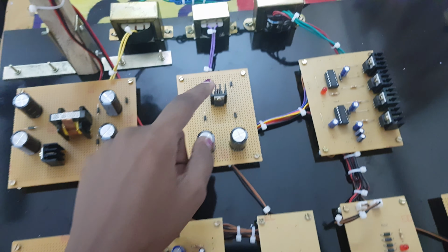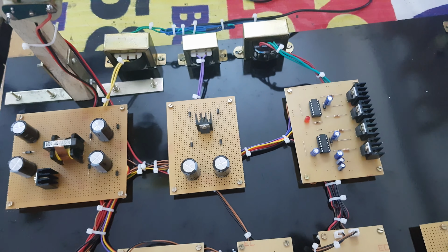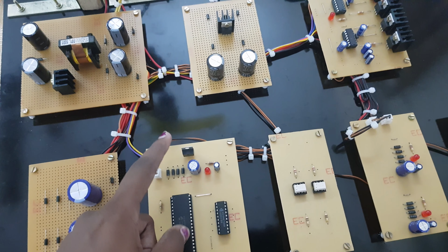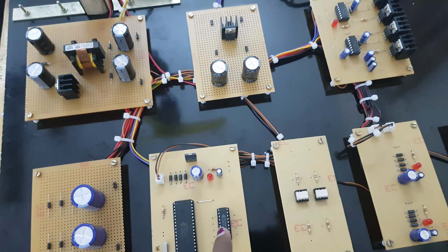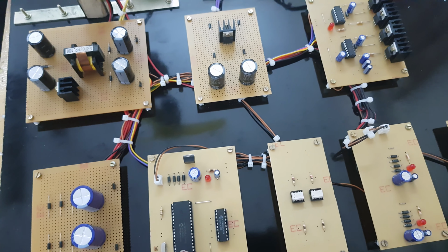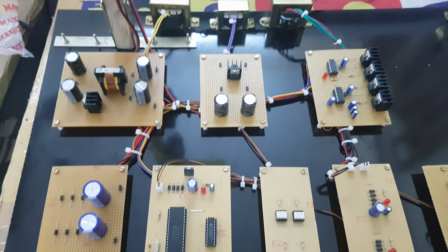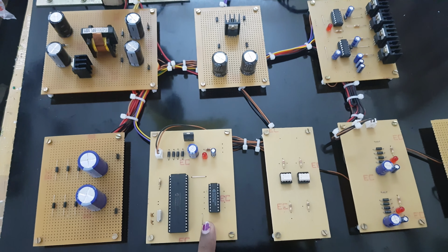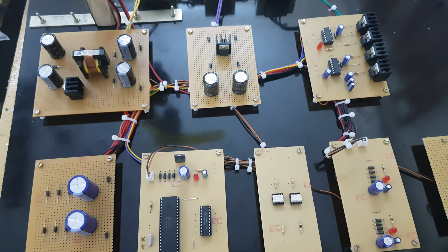So we are using a 12 volt transformer over here, which is used to step down 230 volt to 12 volt, and this 12 volt has been passed to this microcontroller board, where it contains a voltage regulator which regulates 12 volt to 5 volt, and this 5 volt has been passed to the microcontroller as well as the buffer circuit. Due to the 40-pin configuration of the microcontroller, when the current from the transformer is passed to the microcontroller, it gets split up. So the output current from the microcontroller will be very less. In order to amplify it, we are using a buffer amplifier over here.